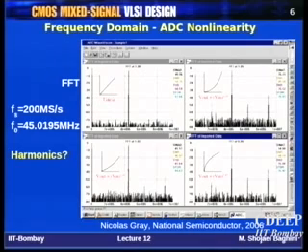That's why it reduces. Anyway, it was just a brief explanation of why you may not get exactly the same thing. But the trend will be the same: if you increase the number of samples, you will get a linear improvement in SNR for an ideal ADC.